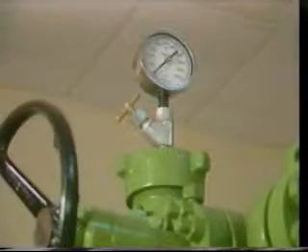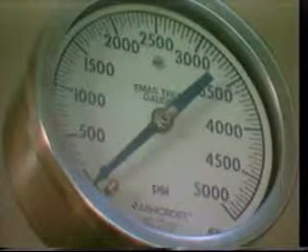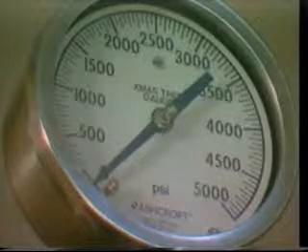A pressure gauge is installed in the tree cap to enable flowing and shut-in wellhead pressures to be recorded. All equipment in the vertical run from the tree cap to the tubing must have an inside diameter equal to or greater than the outside diameter of the tubing. The next component of the Christmas tree assembly is the production choke. The choke is used to control the production rate.